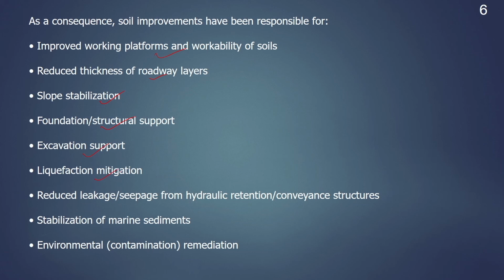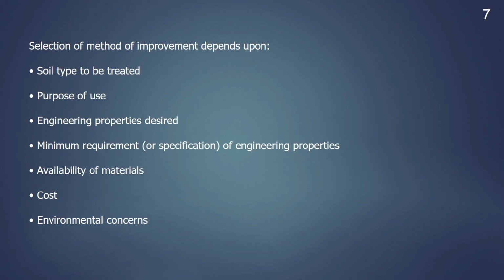It gives liquefaction mitigation. It reduces the leakage or seepage from hydraulic retention or conveyance structures. It stabilizes the marine sediments, and it can also be used for environmental remediation, mostly contamination remediation. So, soil improvement using the chemical methods can have all these implementations.